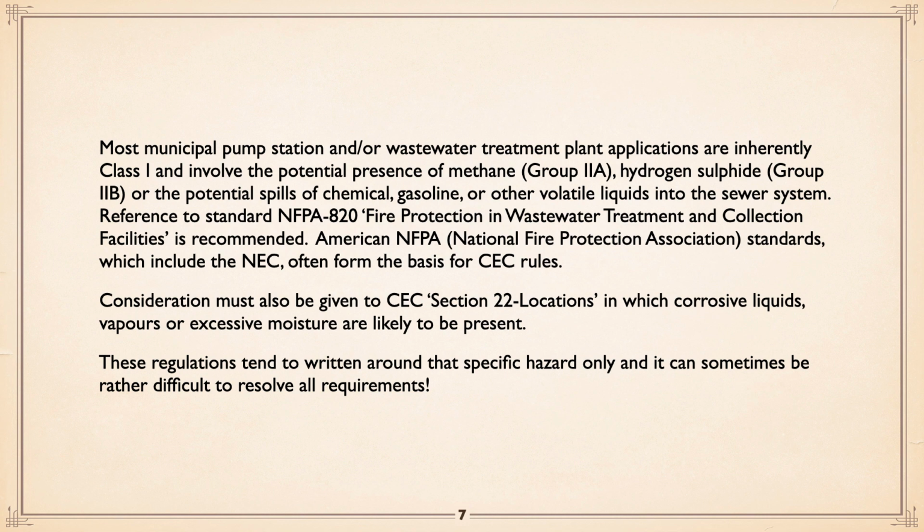And under NFPA 820, I'm recommending that be checked into. Take a look at it. NFPA standard, which includes the National Electrical Code, which is the basis for a lot of the Canadian Electrical Code. It also gives Section 22 locations, in which corrosive liquids, vapors, or excess moisture are likely to be present.